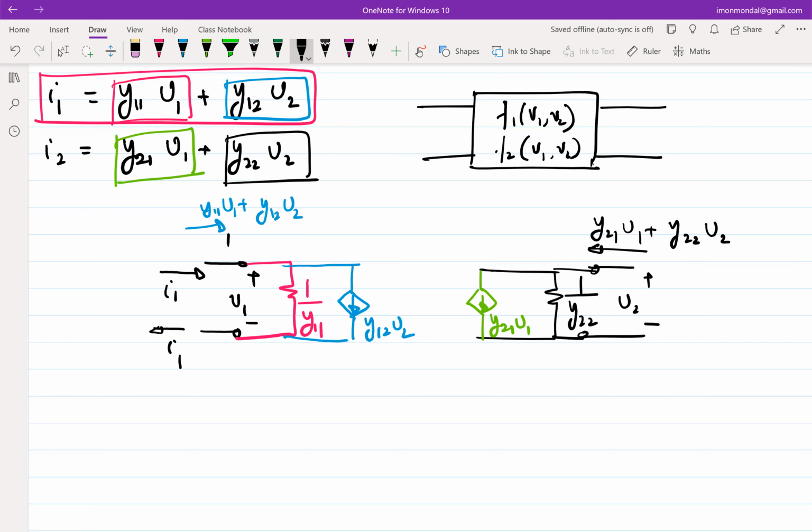You have voltage sources, current sources, and this network sitting there, biased properly, biasing is given. So now talk me through the algorithm. How will you go about extracting it? Let's take Y11 to start, incremental Y11. What will be the algorithm? Port 2 should be short circuited, not in the incremental sense, in the total sense.